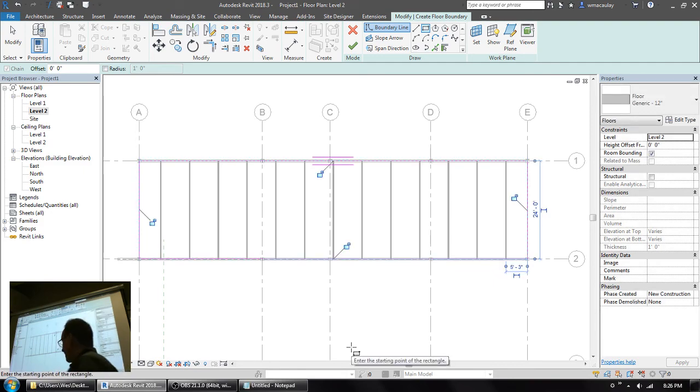And I'm sure that in times past, you folks have seen this symbol in your floor sketch and just ignored it. And of course, it means the same thing as it does when we were making the beam system a few moments ago. This symbol means the span direction of this floor. Now, for an architectural floor, it doesn't really matter, but now it's kind of going to matter, because we're going to be showing you how these steel decks with concrete on top are created in Revit.